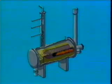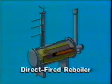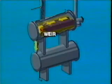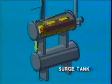Reboilers can be direct fired or heated by steam or hot oil. The direct fired type, containing a removable firebox and fire tube, is normally used. An overflow weir maintains the glycol level in the reboiler. Excess glycol spills over the weir and flows downward into the surge tank by gravity. When the glycol level is low in the surge tank, fresh glycol is added to the reboiler, so it can be dried before going into the surge tank.